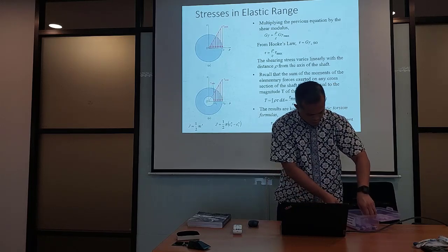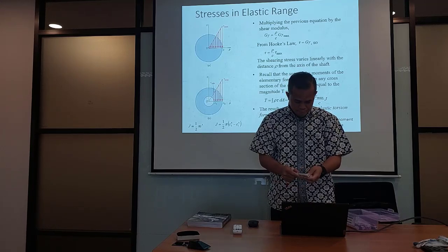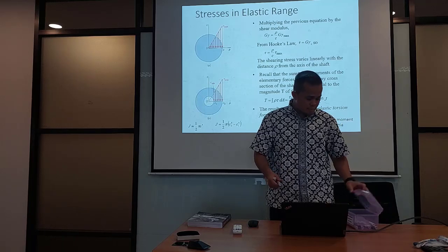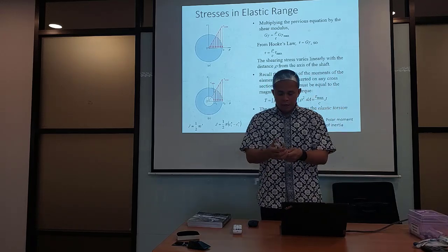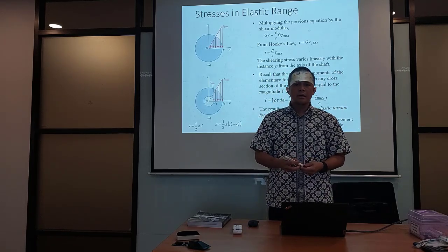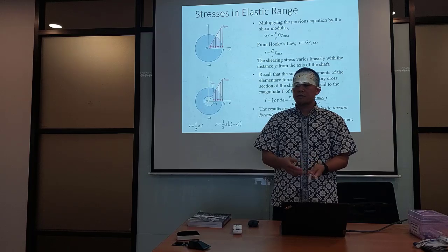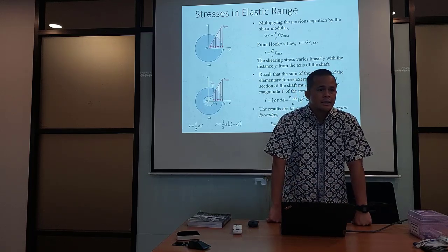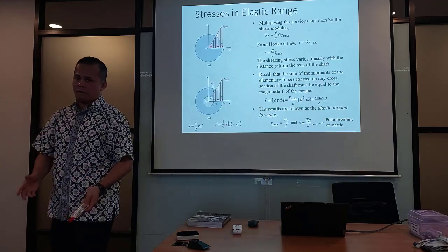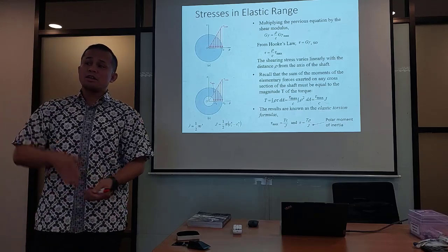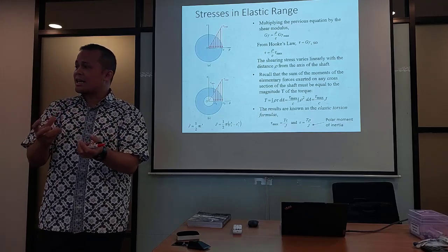In the last meeting, we discussed how we can define the shear stress because of torsion. Shear stress is symbolized by tau. What is the formula of shear stress? That's the general one. If it is generated by a torsion, the formula of shear stress will be Tc over J. T is the torque applied to the shaft, and it is the internal torque. Then you need to section the shaft to understand what torsion is generated inside the shaft.